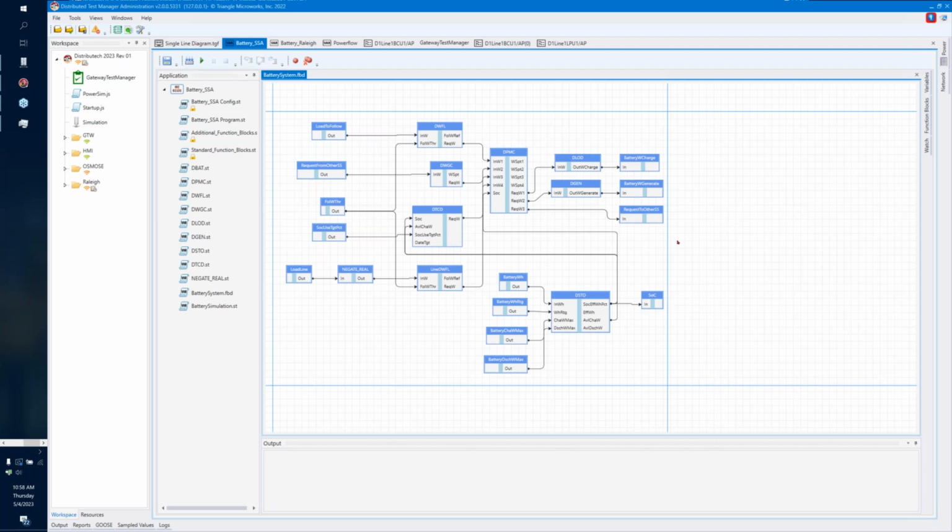With that, let's walk through what a function block diagram looks like. In this case, you'll see that we've associated function blocks with specific logical nodes. If these don't look like the logical nodes that you're used to, this demo application that we put together is for a DER application, specifically battery systems. But there are no specific rules defined as to how you need to use these function blocks. Do they need to be associated with a logical node, or can you just write your logic however you like, with ands and ors and counters and the other building blocks that are part of the 61131 standard?